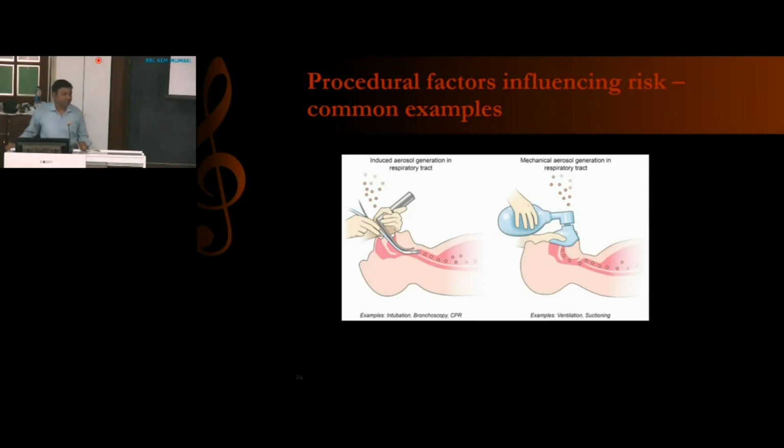That is mainly the engineering point of view, that the whole volume of air in a particular room is completely replaced by fresh air. That is one air change. Understood? So whatever we have exhaled right now is present in this air, and when completely new air comes, it comes through these ducts. So we have artificial ventilation for this room, even the ACs.